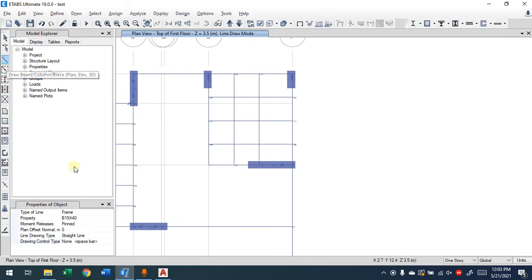By drawing line. Remember, the pin is important, the section is important, and then if you want points, you can use the reference point. If not, you still can go with the quick tool, quick draw, but you have to join them later together, and still you need the first one in order to draw over the grid line if it is necessary. I believe this is enough for the secondary beams if you have a system in this manner. Thanks for watching.